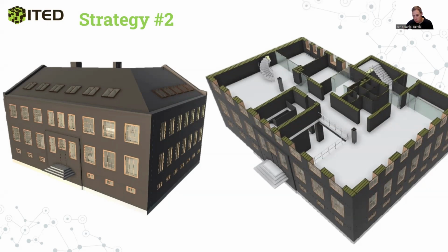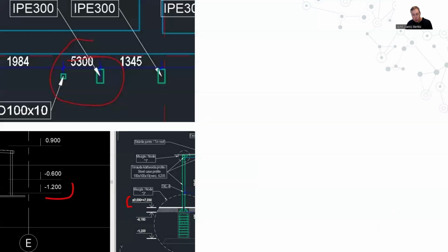So the process is, as we took the drawings, we created the 3D models from them, analyzed if there is enough information in the 2D drawings to create the models, and then we combined and analyzed the models in the 3D environment again. So during this process, when you create models from 2D drawings, it's very easy to find mistakes that do not allow for successful creation of the models, but also they wouldn't allow for construction.